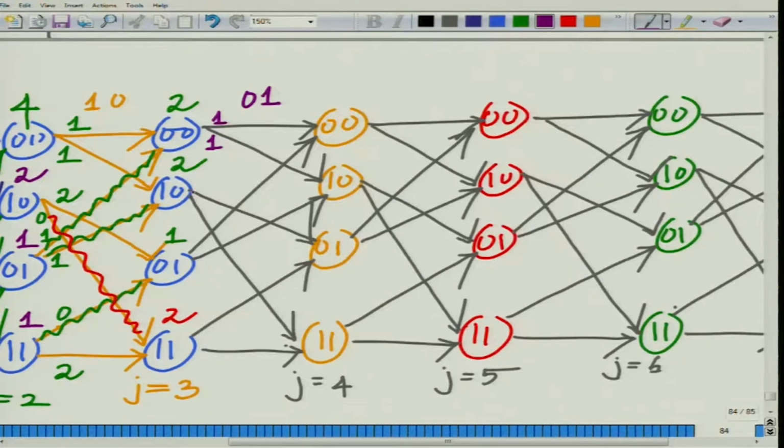Branch metric corresponding to 1 0 because it will be 0 1, top one is 0, output 0 1, so this has a branch metric 0, bottom one will have a branch metric 2. 0 1 it's 1 1 and 0 0, so again branch metric will be 1 1, and here again 1 1 1 0, so branch metric is 2, and lower branch will have 0. The minimum is 2 plus 1.